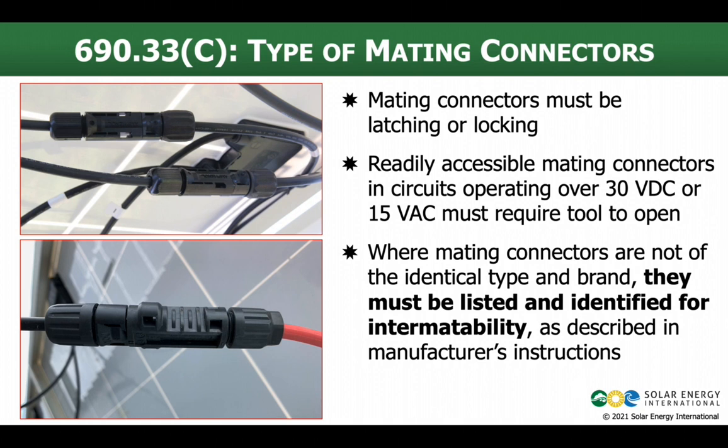They basically reverse engineered it and said, hey, we made one that'll plug into this other dominant brand that's out there. So this can be an issue because, depending on how well they reverse engineered it, it may actually not mate at all. And we've got problems, as I've described already. So this is a really important one to pay attention to. You're not going to find many connectors right now that are, in fact, listed as intermatable. There's not a whole lot of them out there.